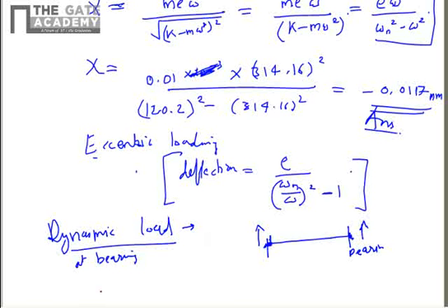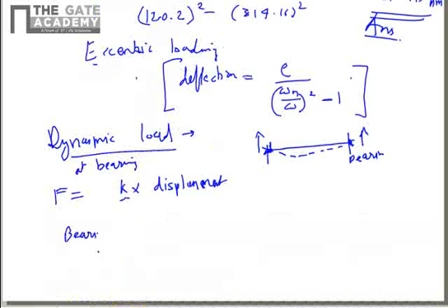So you know the dynamic displacement of the shaft, and if you multiply the stiffness k of the shaft with the displacement, the stiffness we are talking about here is the bending stiffness, then you can get the forces at the bearings. So the bearing force will be equal to the force due to flexing of the shaft, that is the bending stiffness multiplied by the displacement, which is 0.0117 that we saw in the part 1 answer, and the K was 147.27.